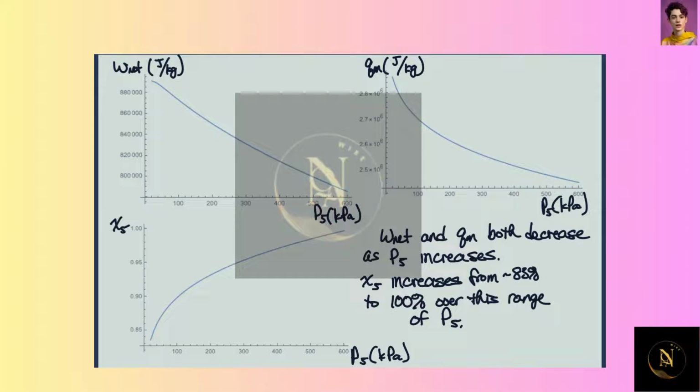But the efficiency is going up because you can see here that the specific heat we need to put in initially drops faster than the work does, and so that's why we wind up with a peak efficiency, which is the ratio of these two things, right around here.